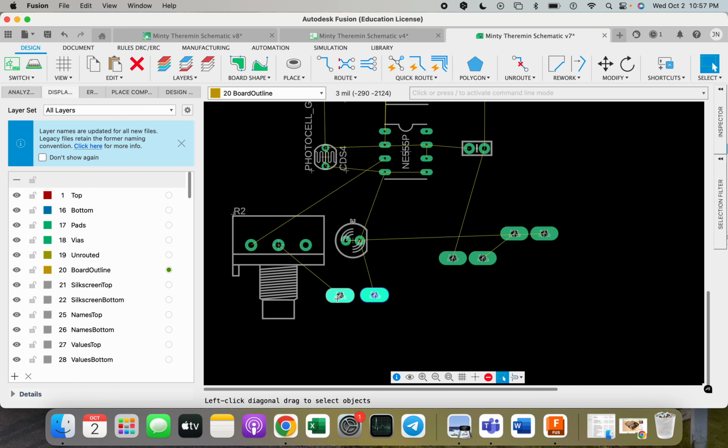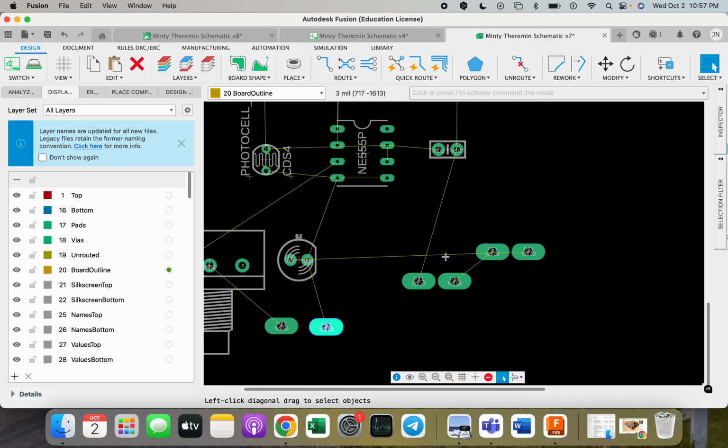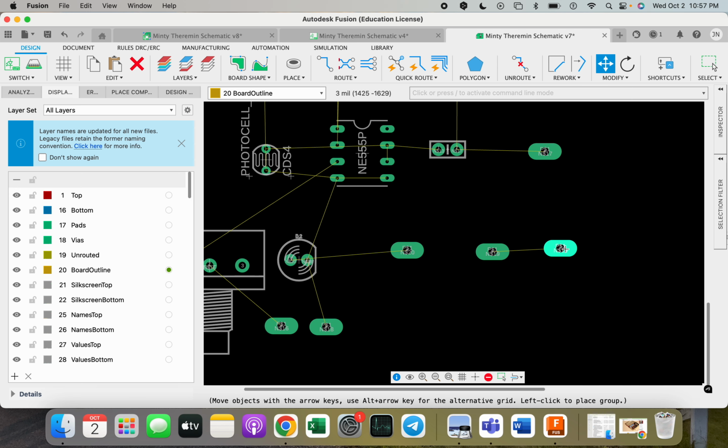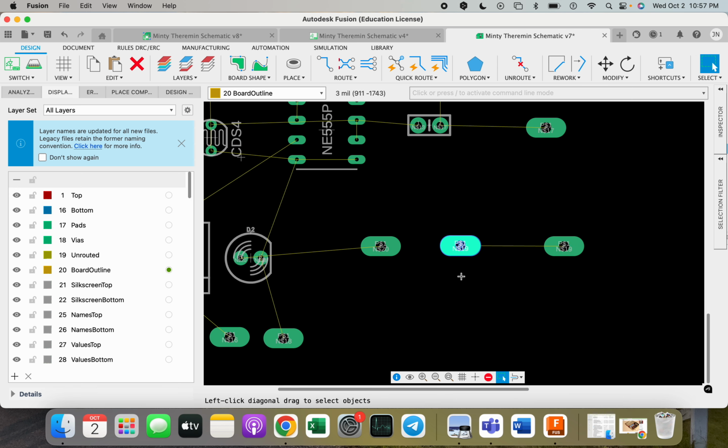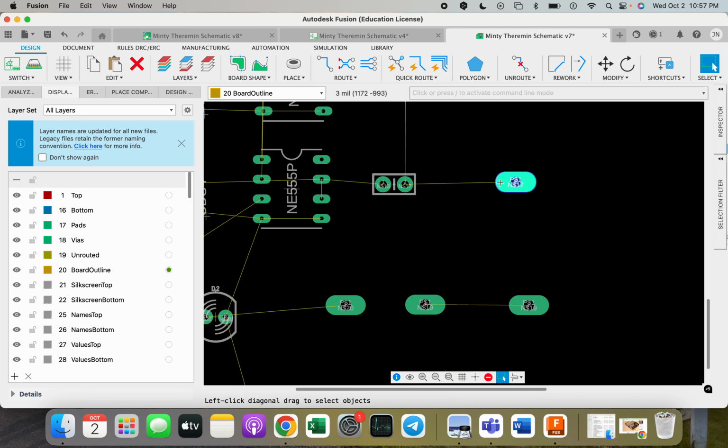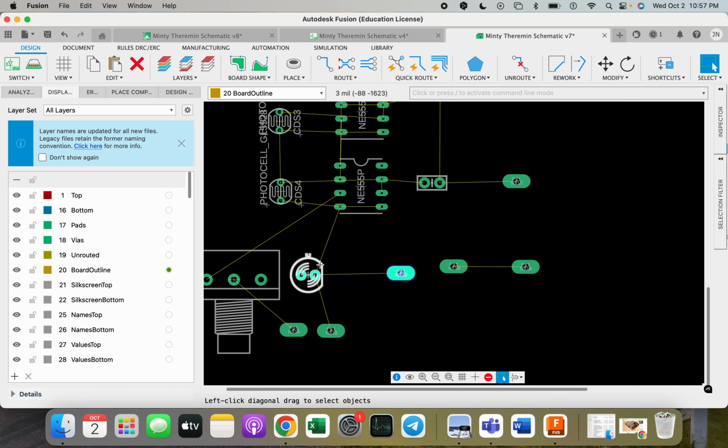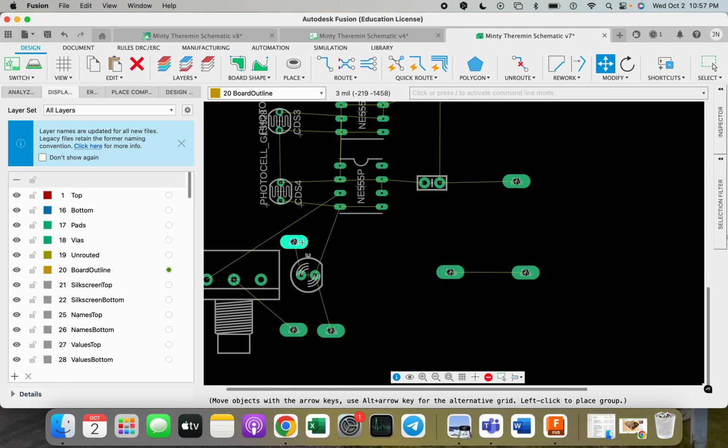So off of the potentiometer, this is the speaker, and then that's the speaker positive. Here off of the capacitor, this is most likely our positive, and then off of the LED, actually, this one here will be our positive connected to the LED because this is the negative side of the LED.